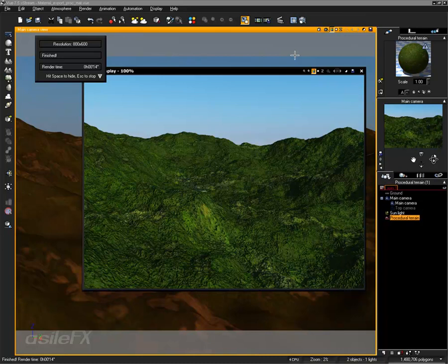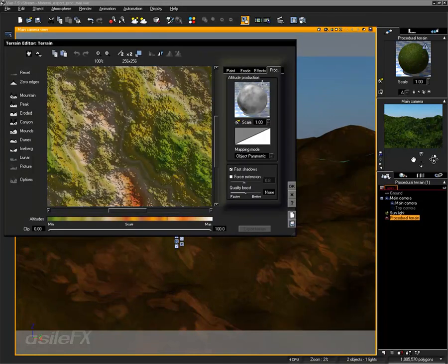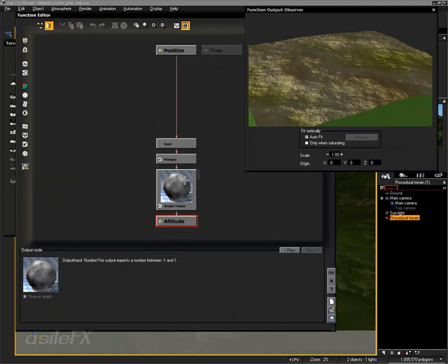But of course, once again, that bump coming from the procedural terrain is really, really intense. So whether or not I want to modify the material a little bit more to get rid of the intensity, or I could go in and decrease the roughness of the procedural.